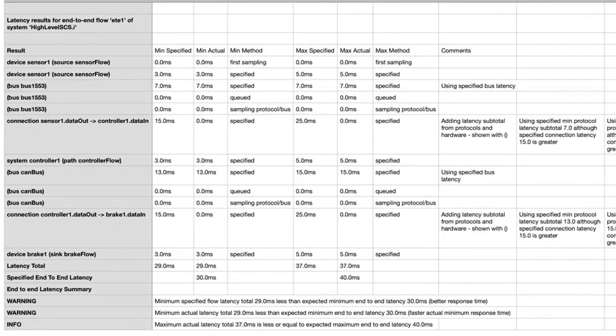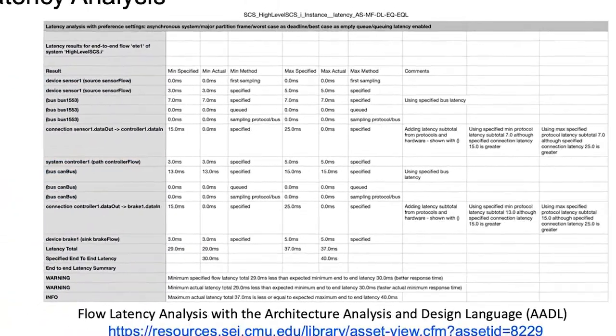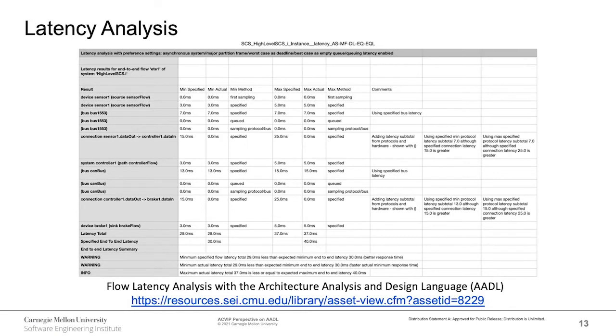The topmost line of the analysis shows the settings that were selected. Min and max columns represent ranges based on certainty. If a component has a metric specified, it will be listed here. The totals will be shown at the bottom to calculate expected latency. The left-hand column of the report shows items to which latency metrics are attached. The analysis itself shows how components interact with each other, similar to integration testing, which is usually not done until vendors bring in all components or parts together for assembly.